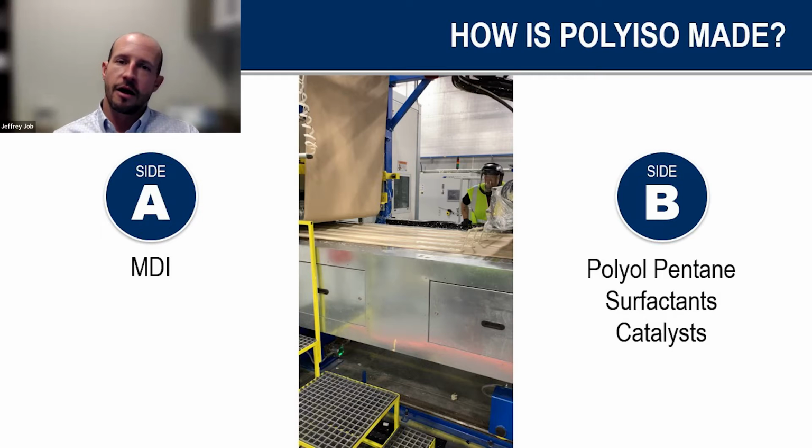So on a lot of adhesive, it's going to typically have a range of coverage based on how tight the pattern you're putting down, how much you need to put down based on typically the uplift requirements of the system. If you're using a paper facer, you're going to be on the lower end of whatever that range is, just due to the fact that it's going to absorb more of that adhesive.